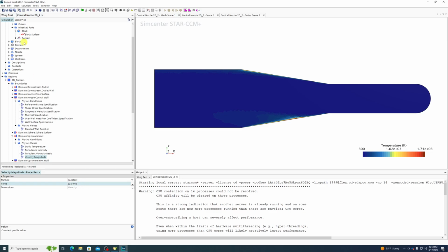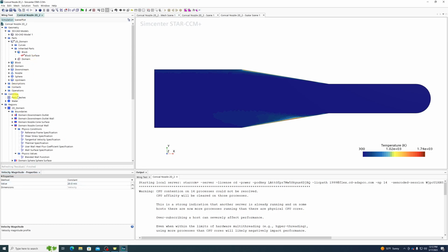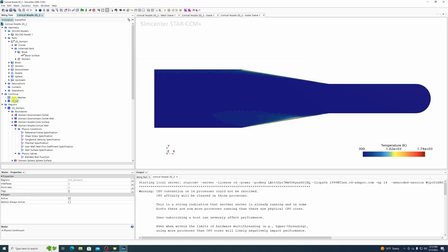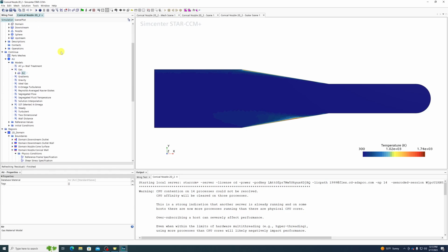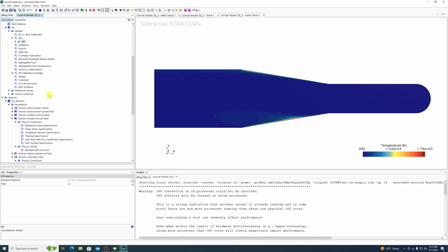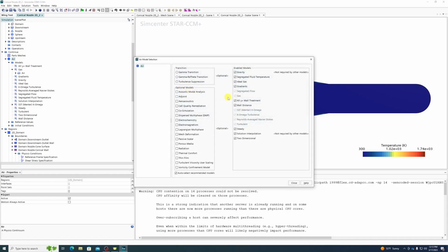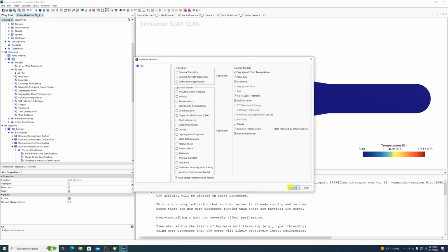I'm going to give it 20 meters per second. So I'm going to make this very similar to what we have for... Oh, I did turn this into air. Okay, this is no longer water. This is air. Let's just verify that really quickly here. It says this gas is air. Perfect. That should be fine. Really don't need gravity, so I'm going to turn gravity off. We're running left, right, more or less parallel to gravity, I think, or along iso lines of gravity.